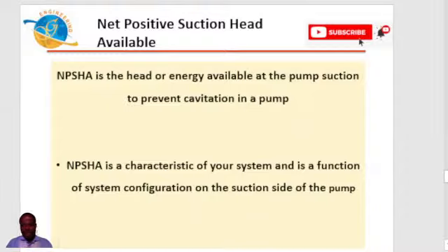Don't forget I said that centrifugal pumps generally are not capable of handling large quantities of vapor. So your pump's external suction system, it's a must, has to be designed in such a way that it provides sufficient absolute pressure, absolute head, absolute energy, to prevent any form of vaporization, any form of flashing in the impeller by the time the pump is put into operation.